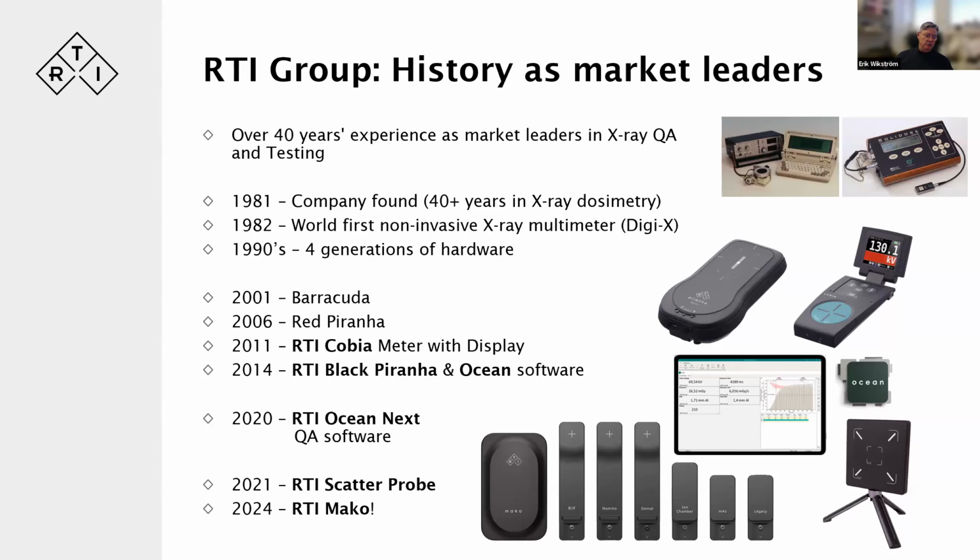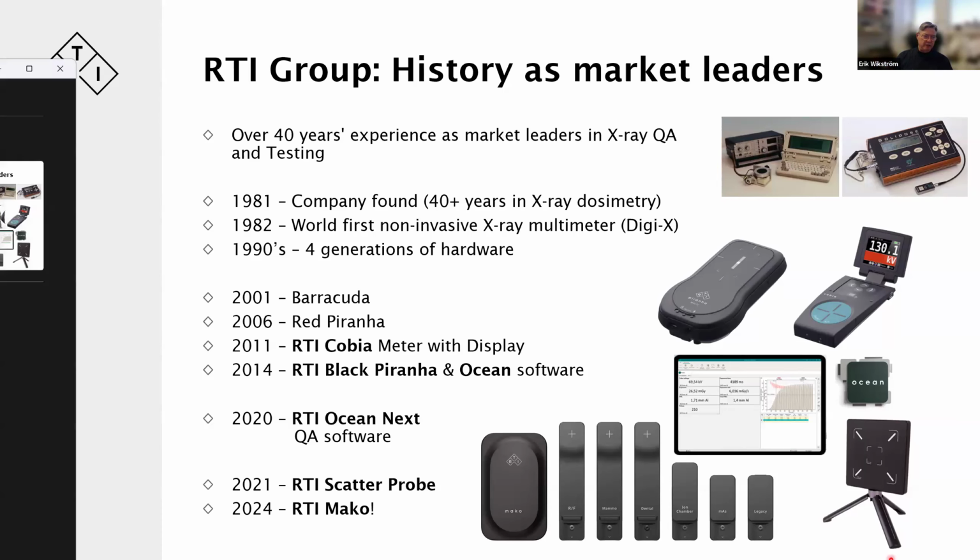And before that, of course, to measure kV, for instance, in an X-ray machine, you had to disconnect the high tension cables and fit them into a voltage divider, and then make a measurement, connect your oscilloscope or a voltmeter, and then put everything back. So that would take, in the best case, like 30-45 minutes for one exposure. Being able then just to put the detector into the field and make one exposure and have all those data in 2 minutes was a vast improvement, of course.